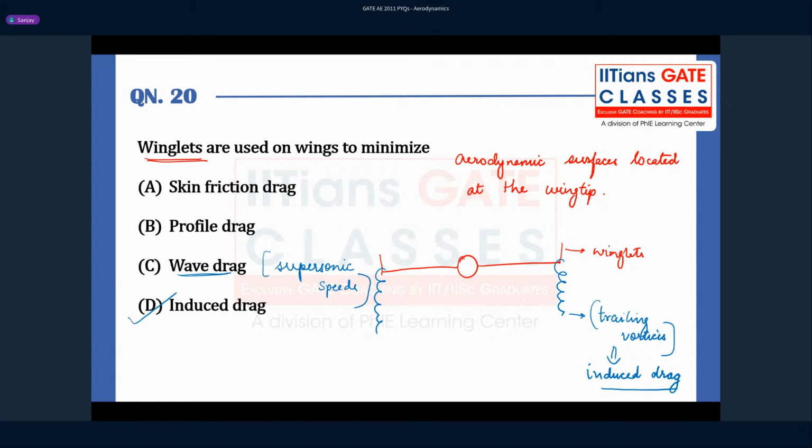So when you have supersonic flow of air and suddenly it is terminated by a shock, your velocity is going to be reduced to subsonic speed, right? So that sudden drag is the wave drag. And what is the profile drag? Profile drag is a combination of all such drags like your skin friction drag, your form drag, your interference drag, right? They are all due to the components of the aircraft. They are not associated with winglets. Winglets are not used to minimize the profile drag.